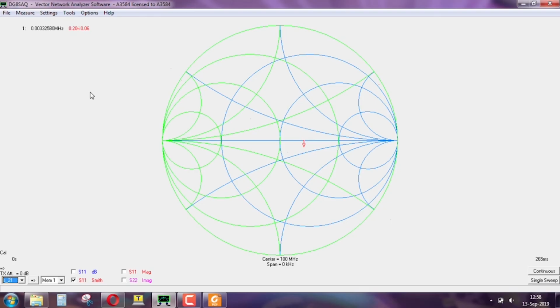Close to the center. You have to believe me if I say that it is impedance matched, close to the R equal to 1 circle. Maybe we need to calibrate with the exact connector. So in practice, every minor detail will matter, but being the electrical engineers we are, let's deliberately do something.